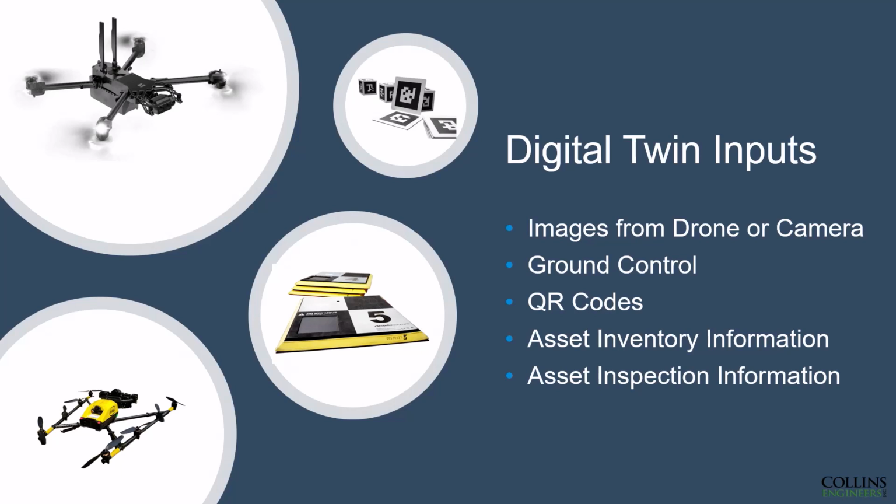And then lastly, there are quite a few industry advancements in kind of the digital modeling that are coming to, accessories, I guess I'll call them, to aid the modeling and create a more reliable product. QR codes, most photogrammetry products now will auto-identify QR codes and create automatic tie points to create the model. So we've been using those on most of our inspections, and it just creates a much more reliable model in the end. And then ground control points, like what you see here, provides a survey control point target for input into your model and processing.